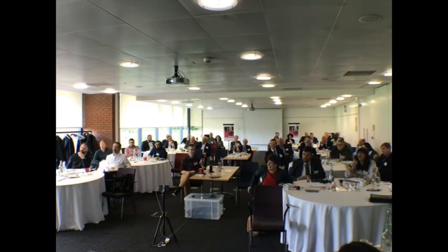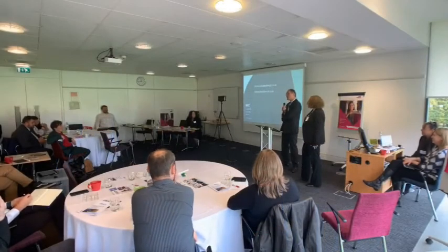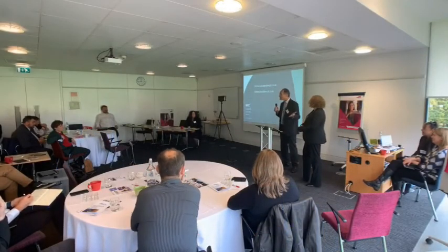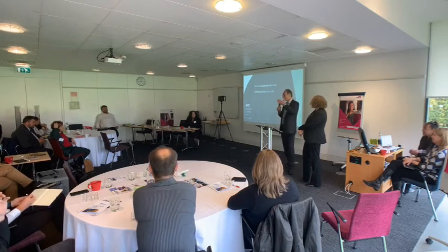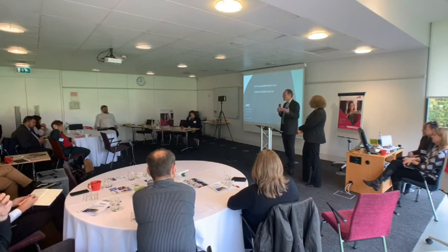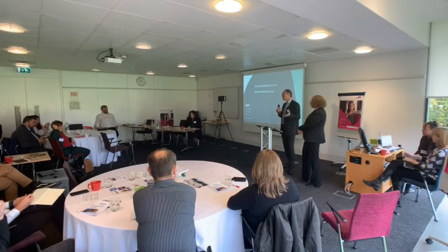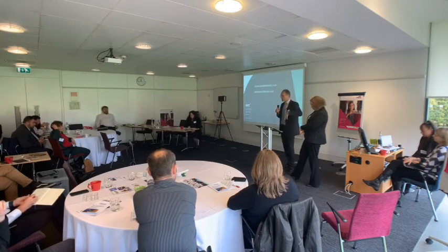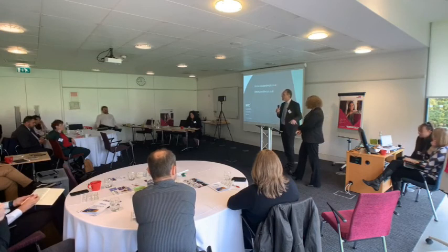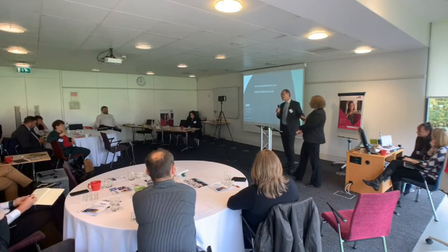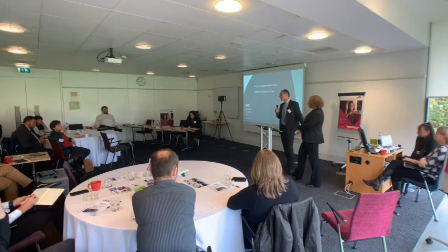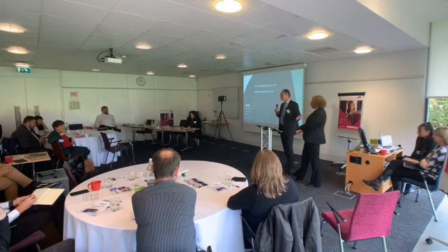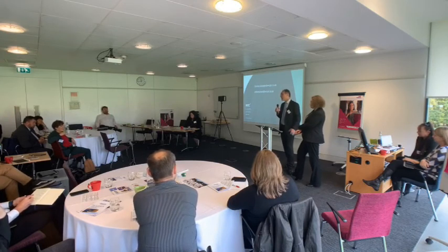I think it is just genuinely that there's not the anecdotal evidence probably that they're a problem. As I mentioned, they tend not to fail. And leakage, very often we find leaks, and the water is just disappearing into the backfill and running away. We've found leaks of the order of 5 megalitres a day. That's frankly a burst almost, and there has been no evidence above ground of that occurring. And that's not just an isolated case.